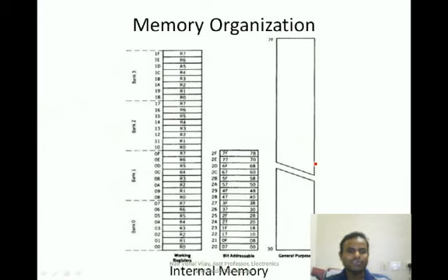So basically, as you can see on the screen, the internal RAM is divided into 3 types: 32 bytes are your register banks, then you have 16 bytes of bit addressable registers, and then you have the remaining around 80 bytes which are byte addressable only by their memory location. So this is what classifies the internal memory.